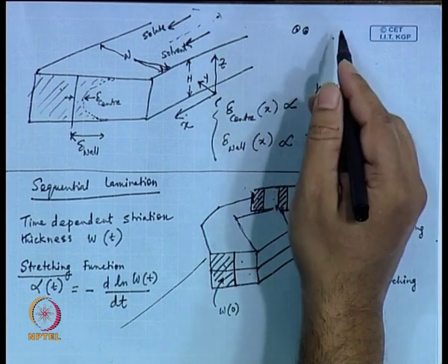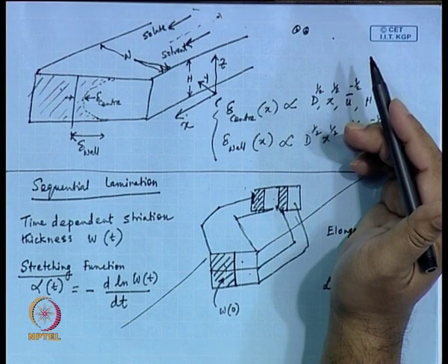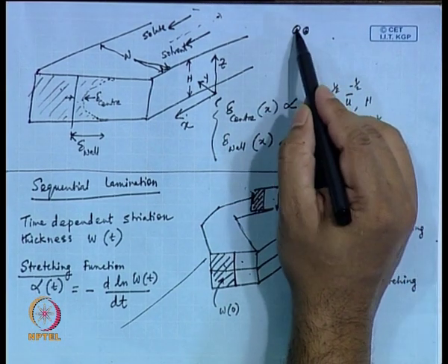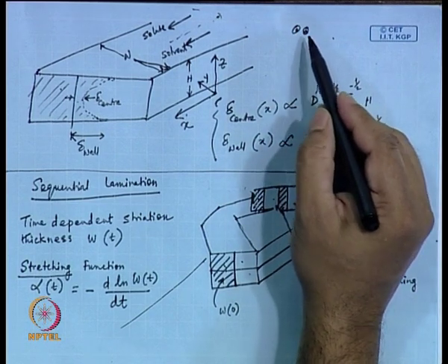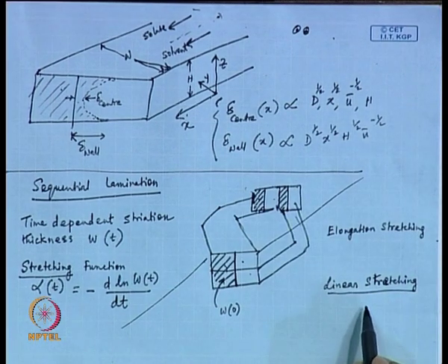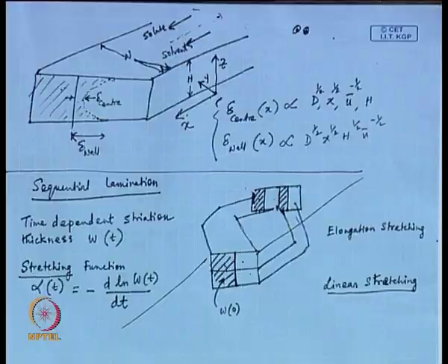Then I will consider that mixing has taken place. If the 2 neighboring points remain as neighboring points, then that is not helping in mixing. So, when we introduce this stretching function, we are trying to find out how these 2 neighboring points are stretched. The linear stretching is what we encounter in a viscous flow: one layer sliding against the other. One point is near the wall and another point is next to it. Because of the velocity gradient, they move at different velocities, so I have a stretching. After some finite time T_f, these 2 points are located at different places, and we consider the distance between them.